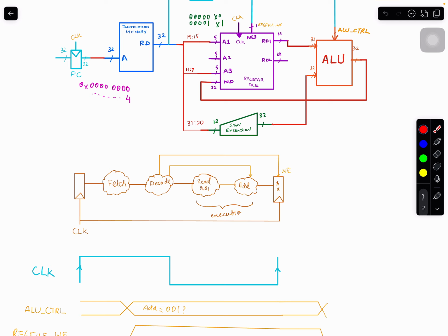All right. And we are assuming whatever frequency we pick later on, if we pick 100 megahertz, which means this time is 10 nanoseconds, that this data going through all this is available and stable here a little bit before this edge in 10 nanoseconds, so that we can say it runs at 100 megahertz, this ADDI instruction.